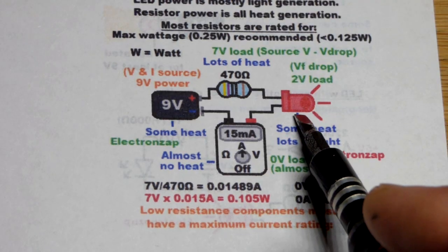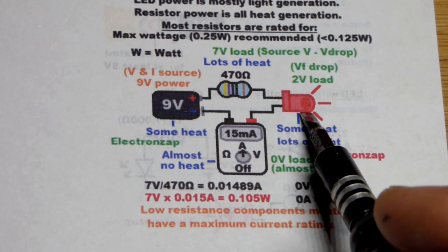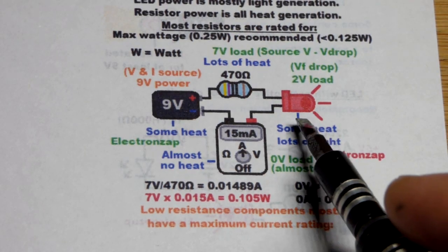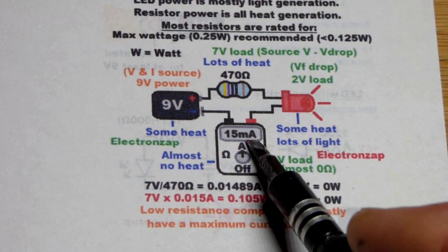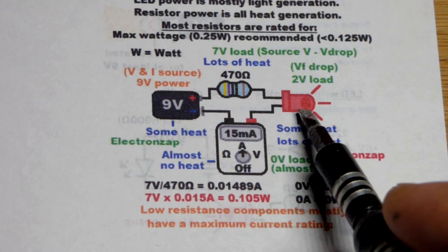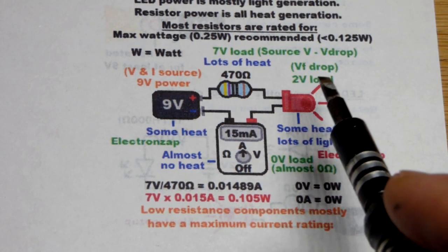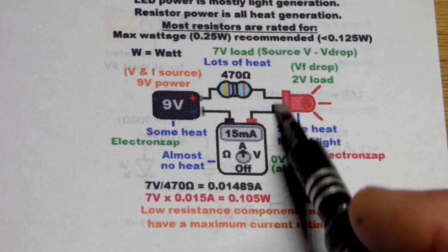At about 20 milliamps of current, it's going to get fairly hot, and you don't want to go above that. That's the maximum. At 15 or 10 milliamps, it'll be cooler and it'll last longer. It just won't produce quite as much light, but 15 milliamps will probably produce close to as much light as 20 milliamps. 10 milliamps isn't even too bad. With other LEDs, other colors, you don't even need that much current. Be aware of that. How much current is flowing through the LED is going to determine how hot it gets because it maintains a certain voltage across it.